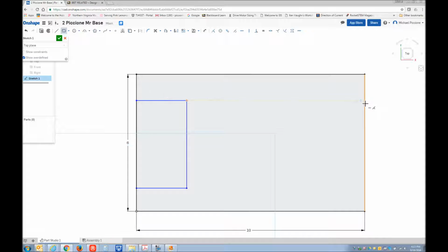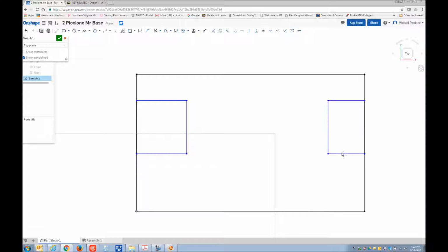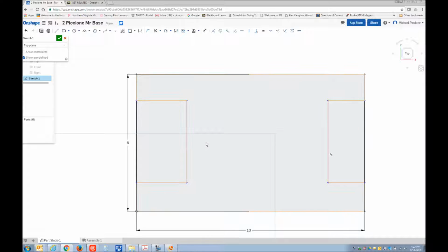So I'll click and start the line there, and then I'm going to go over and pull the horizontal constraint again. So I go to the other side for the intersection, hover, and then slowly pull back, and I get the dotted line signifying that my edge is constrained. And I haven't dimensioned this yet. So now if I click on one, it adjusts both, and that's what we want to see. Now we can go ahead and dimension them.